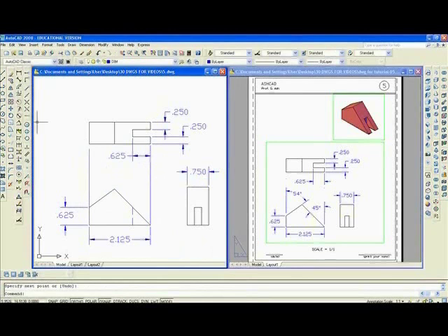And now I'll go to angular dimension, which is here. And you do this counterclockwise. Pick the two lines so you get it the way you want it, like that. Enter to repeat the command. Now I can erase the lines I drew previously.